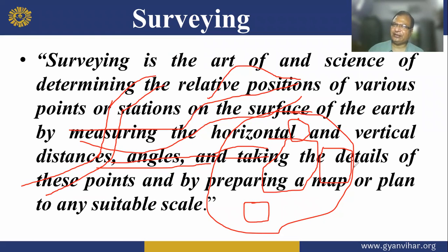What will you measure first? You will first measure how much approach road distance from here to the site, how much boundary distance will come, how much distance of the internal road will be constructed, the length, breadth and height of the workshop, and the location is important.